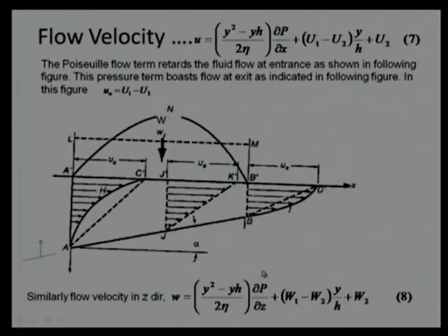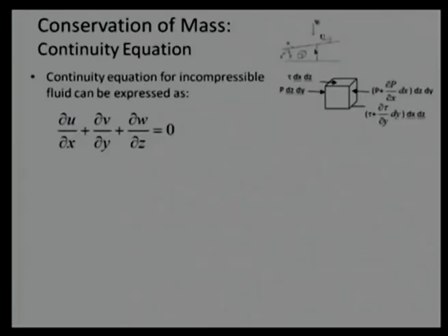We can figure out the inverse, what the pressure will be in terms of velocity. To do that, we require an additional equation, what we call conservation of mass, or many times the continuity equation. That comes out here. We are making one assumption, that the density is not changing, that it is an incompressible liquid.